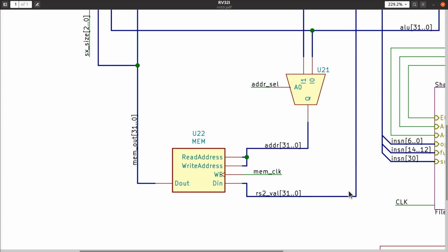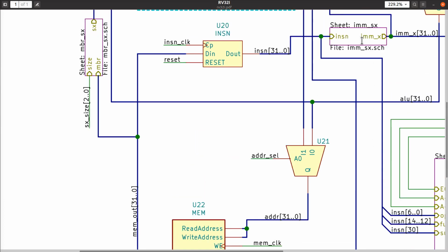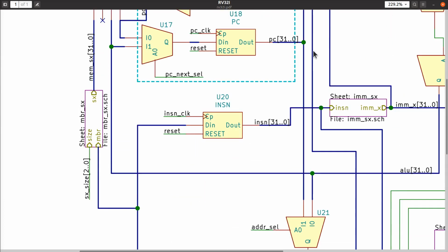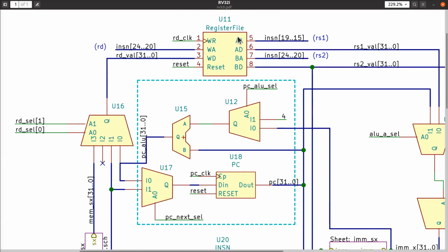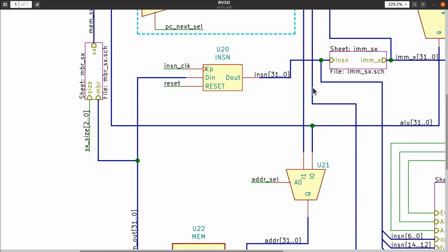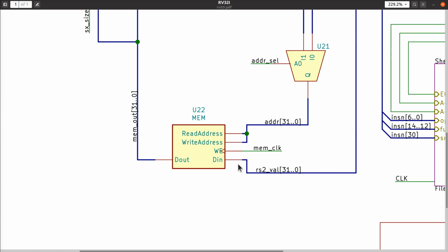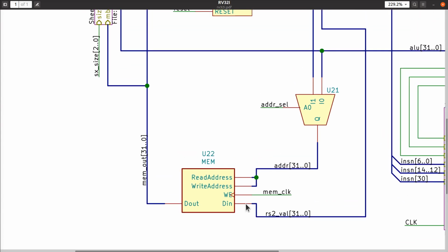As you will see, this bus here moves its way around like this and grabs onto the RS2 output of our register file. So that's just permanently wired onto there. If you're ever going to write anything into memory, it has to only come from the RS2 register. And that seems reasonable because it's the only instructions that we have to do that.